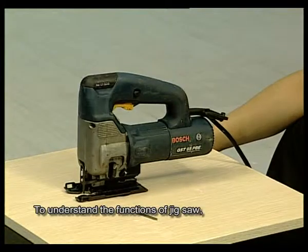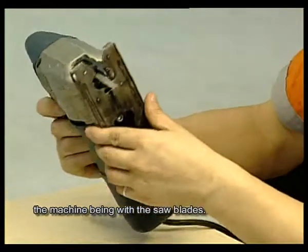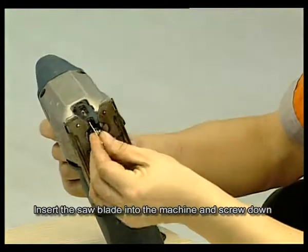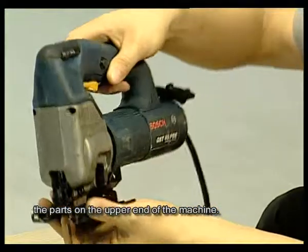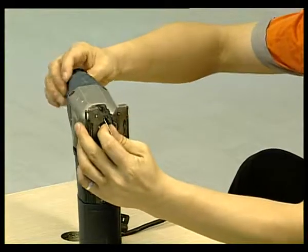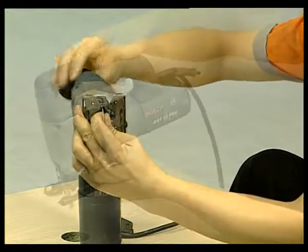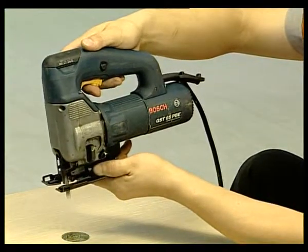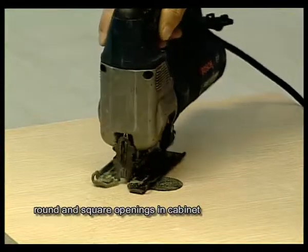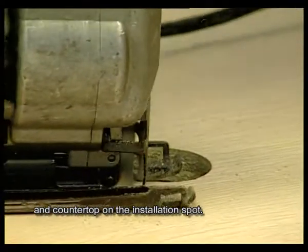To understand the functions of the jigsaw, we need to take a look at a demonstration of the machine with the saw blades. Insert the saw blade into the machine and screw down the parts on the upper end of the machine. The jigsaw can be used for cutting round and square openings in the cabinet and countertop on the installation spot.